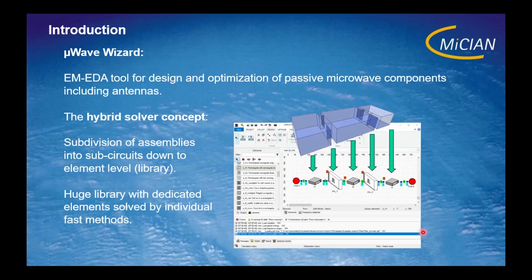In 3D FEM, you create a mesh for your complete design in 3D, and there you match the input and output requirements. 3D FEM is the most accurate solver so far, but it is very time consuming. So we are using a hybrid solver, combining 2-3 solvers together, so at the same time we can improve the accuracy and save time as well.